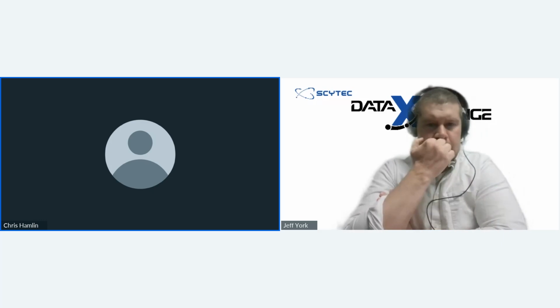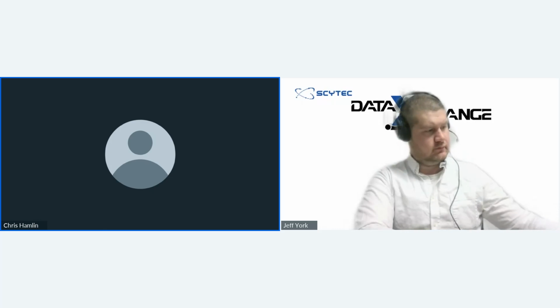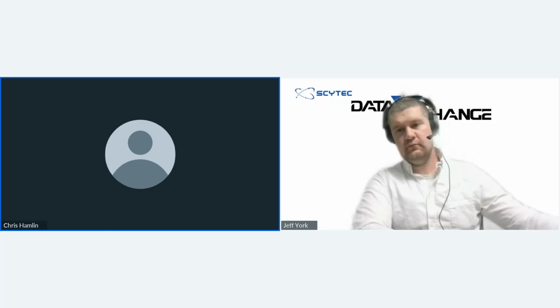So what does that mean from a data perspective, and how quickly am I viewing the data from the machine on these screens? Anything that shows a current status of a machine, like the machine status grid, where you're getting that current machine status with no historical data behind it, so not the timeline or a summary, just the current view, has about a 2-second delay from the machine.